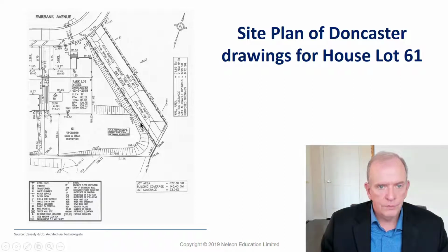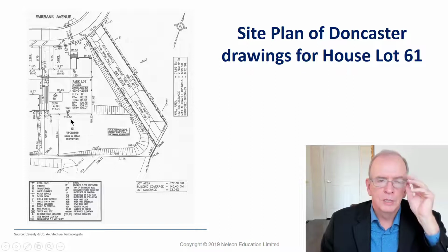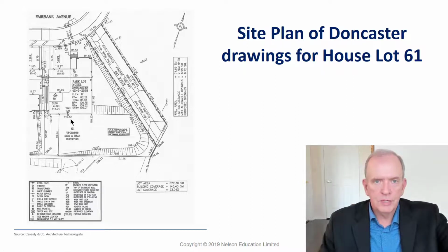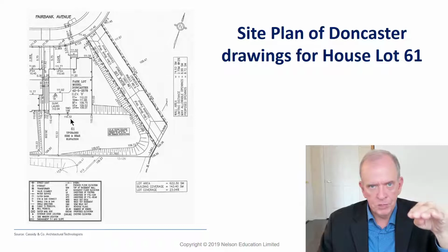There's this runoff area here too that would hit this path, I guess, and run towards the back. And you can also see there's a bunch of elevations that are given, spot elevations. So that's 110.32. Wherever the benchmark is, maybe the benchmark is down the street somewhere and it's at 105. Well, that means this has come up 5 meters from the distance to that benchmark.